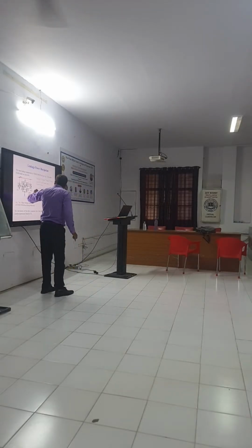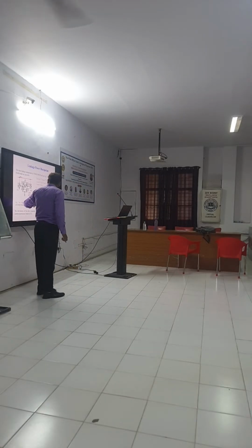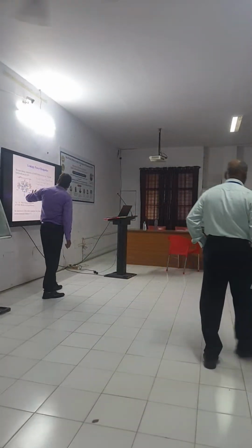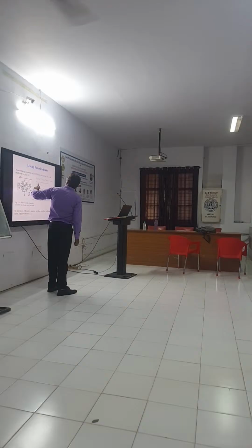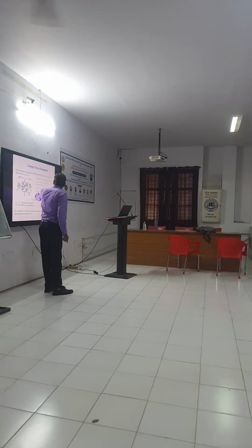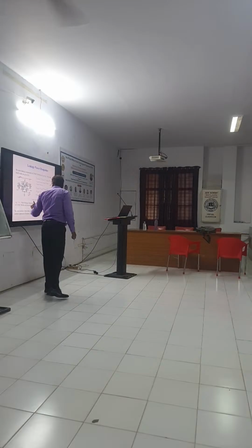So total subthreshold leakage was calculated. Then total gate leakage calculate. Then one more: junction leakage. Yeah. So junction leakage here. This is subthreshold leakage, junction leakage. This is the gate leakage. So this plus this, that is your total leakage.